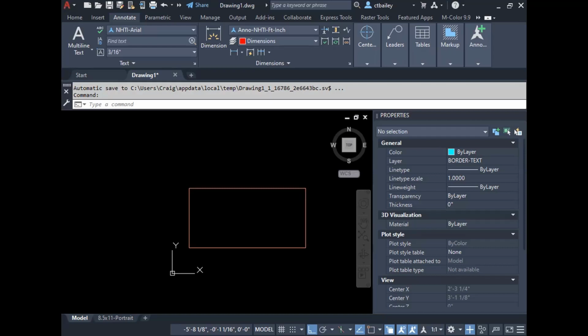Is there a way to make your midpoint at the bottom move with your thing? Right now it's staying in the same old midpoint spot. There is a way to do that. I will show you in a minute, but the way to do it is to bring in the insertion base point parameter and select the base point parameter inside of your crossing selection. And then you have to change its distance to half of your pole.